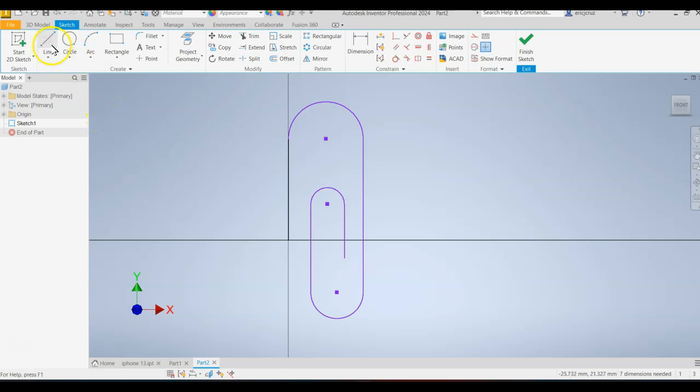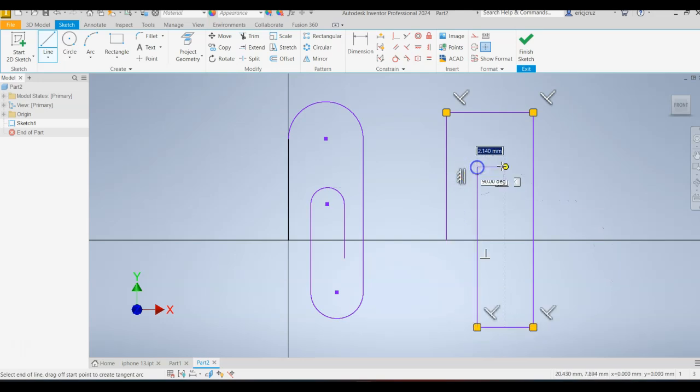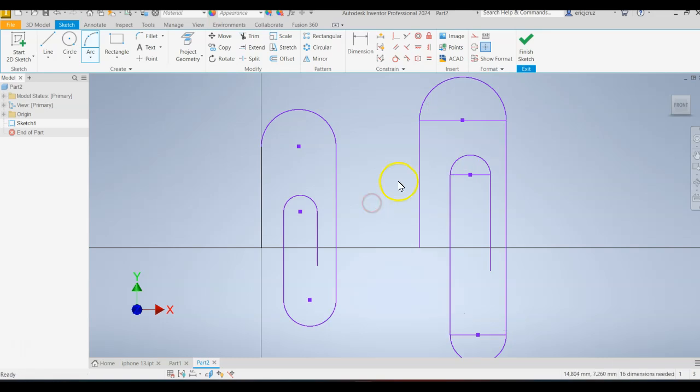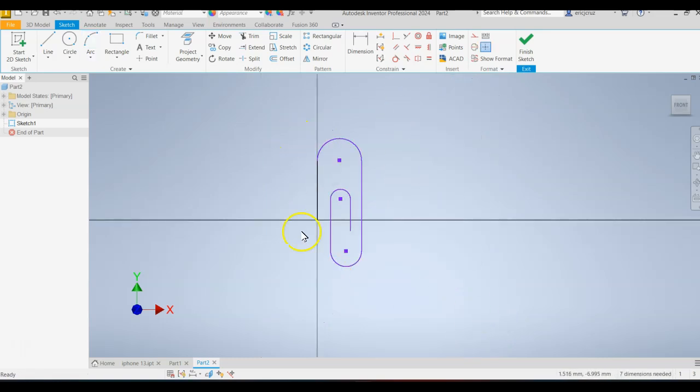And then obviously if it's not working out for you, you can just draw the shape like this, which I think takes longer. Because then what you're going to have to do is click the arc tool, click the two corners, arc it until it says tangent. And this is just kind of annoying. It took longer. Anyways, so once you have this shape, we're going to dimension it.